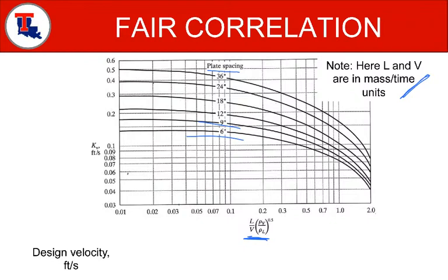Depending on the diameter of the tray, you select a spacing. Sometimes, the manufacturer will give you a diameter range, saying if your diameter range is in between here and here, you select a tray spacing of this. And these are fixed, 6-inch, 9-inch, 12-inch, or 12 inches is basically a foot, foot and a half, 2 feet, 3 feet.